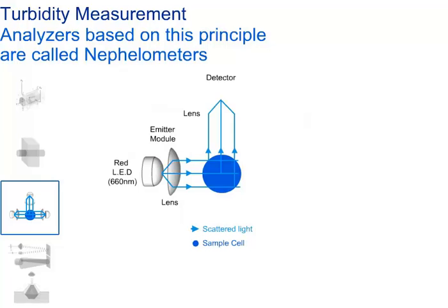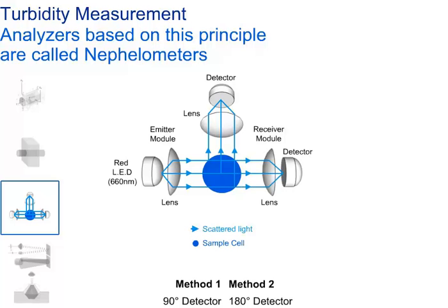Better known as turbidity, nephelometric meters are used in a process to measure particle sizes. This is critical in obtaining a good quality water measurement. There are 2 methods of detecting turbidity. The first, low-level detection, is normally done using scattered light methods. A receiver is placed 90 degrees to a light source and will measure the scattered light from particles within the liquid. The second method is an absorption technique, where the receiver is 180 degrees from the light, and the amount of light absorbed by the particles is directly related to the particle size.